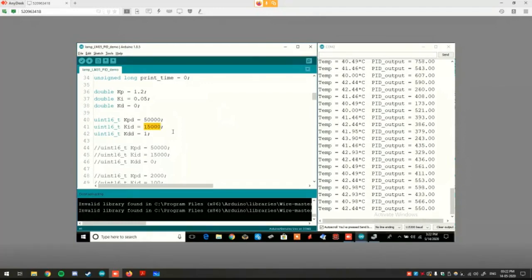As Sawan explained, I first set KP, with KI and KD at 0 initially. Then once I am getting some appropriate response, I introduce a KI term. Once the KP and KI terms almost bring the system to a good response, in this case you don't actually need a D term for this system, but if you do introduce a D term, you get a much better response, right?